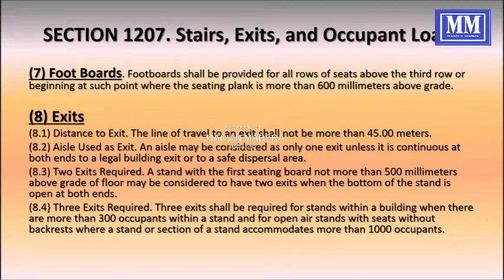Three exits shall be required for a stand within the building when there are more than 300 occupants within the stand, and for an open-air stand with seats without backrest, where a stand or section of a stand accommodates more than 1,000 occupants.